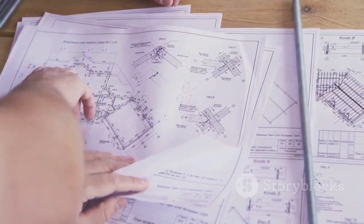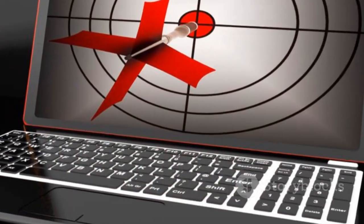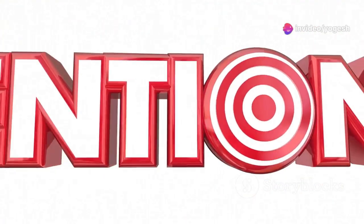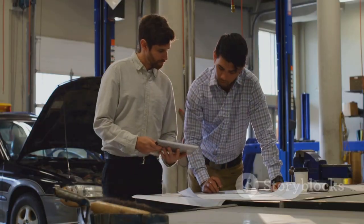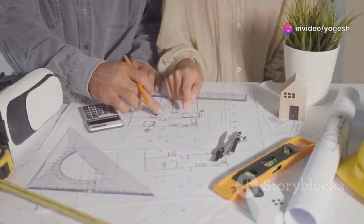For area targets, balance size: large enough for support, small enough for practicality. Always use basic dimensions for target locations, no tolerances. Keep naming consistent: all targets for a datum share the same letter and sequential numbers. Collaborate with manufacturing and inspection teams to ensure targets are accessible and practical.